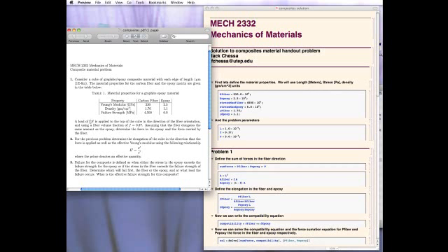of 1 Newton, okay? And we're going to go through and find how much force is in the fiber, how much force is in the epoxy, and then from that we can determine the stress and the strain because we can get the elongation. And then once we have that, we can figure out what's the stress in the fiber and what's the stress in the epoxy, determine at what point they will fail, and then talk about the effective strength of it.